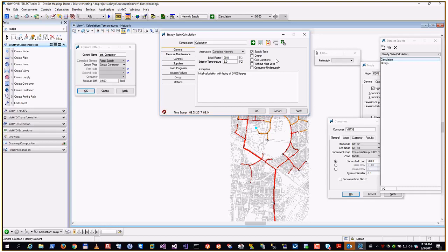Others go just with the length correction factor, which just ignores the pressure losses in the junctions; they would be included in such a correction factor. And one of our users is not using the length correction. They are using bends, and they use the calculation of pressure losses in junctions.